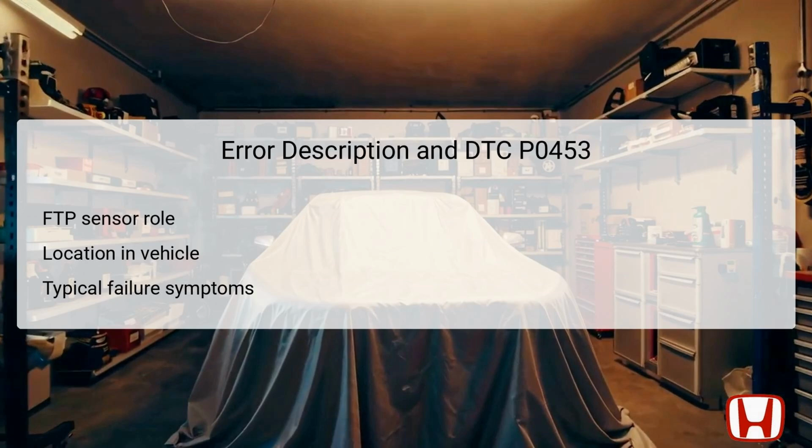DTC P0453 refers to an issue with the fuel tank pressure sensor, which plays a crucial role in monitoring the amount of pressure inside the fuel tank. This sensor affects the evaporative emission control system, EVAP, by sending pressure information to the engine control module, ECM. The FTP sensor is usually located near the top of the fuel tank, connected through a harness. Its primary function is to detect any changes in fuel tank pressure, helping the vehicle's onboard systems minimize evaporative emissions.